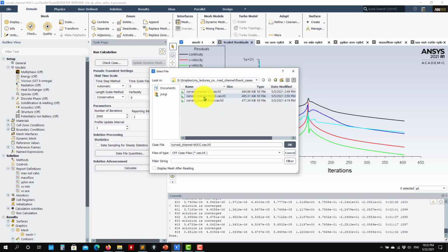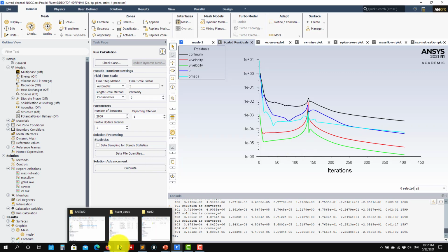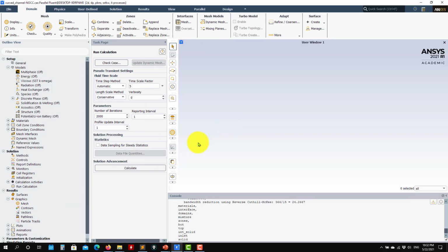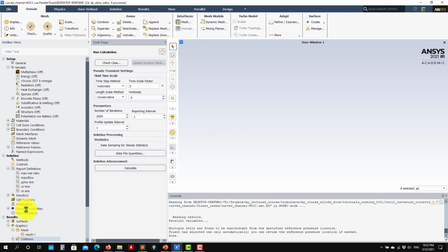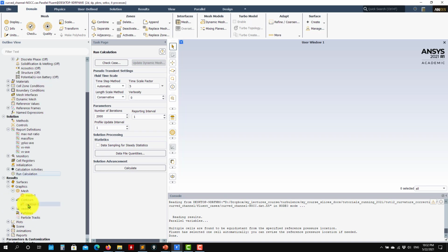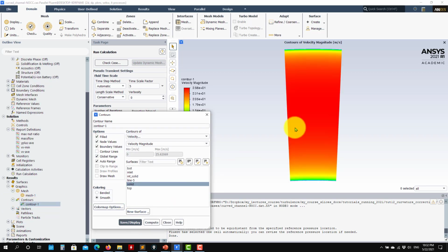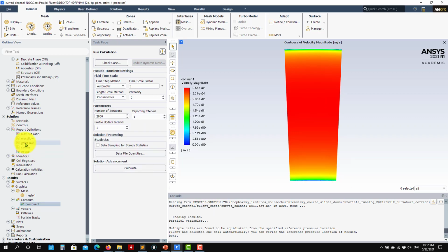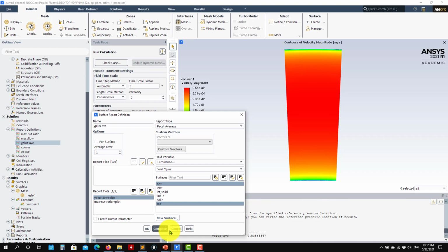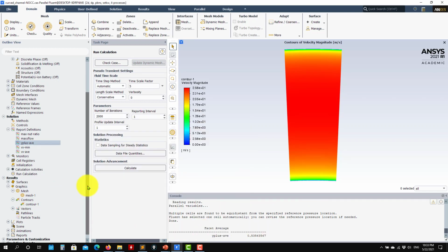Let's open this. NCC means no CC, no curvature correction. You have it in your folders, and let me open the solution and plot the profiles. This is what you have. See that it's a very nice mesh, well resolving. By the way, using this correction does not necessarily require a well resolving mesh; it can be used with wall modeling with no problem.